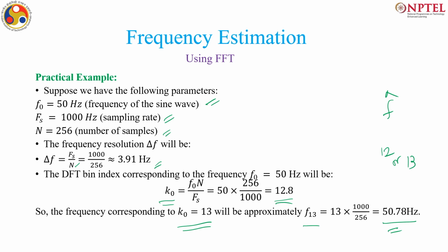Now, naturally this is very good to find the signal if precision is not a big factor, like if you can always increase this n and get a better precision. But if you are trying to find sinusoids like in the broken rotor bar problem, that is 50 and 50.5 hertz separately or 50 and 51 hertz separately, this method may not be very good because you might need a huge value of n. So, there, other methods like MUSIC and ESPRIT will come to the rescue.